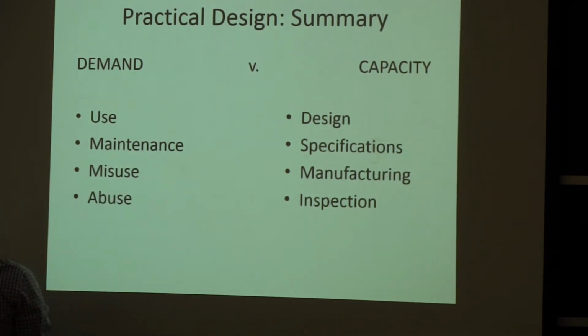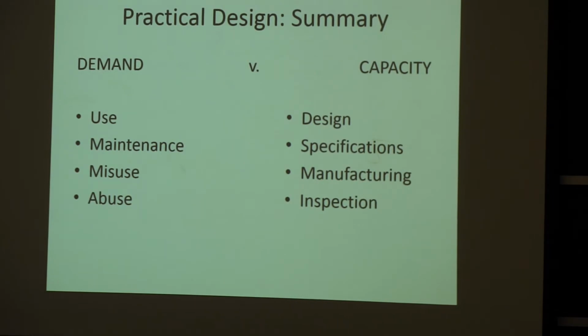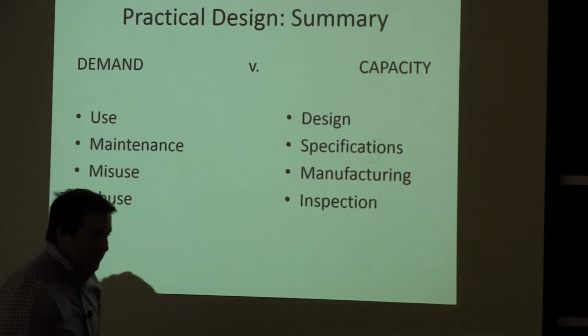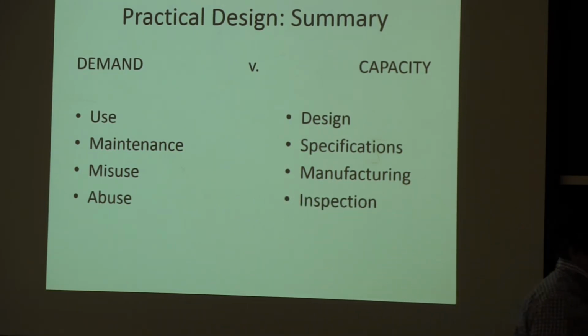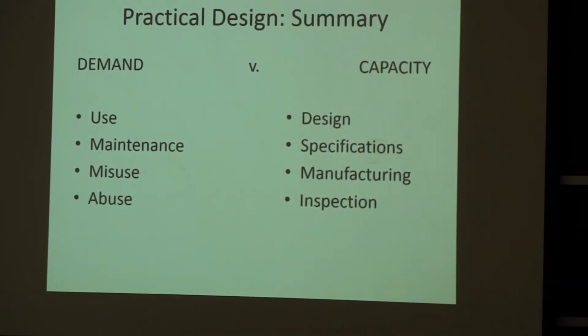If you don't have any quality control, I don't know that you can be sure, if you have a joint, that it will have any significant structural strength. If someone can do the weld exactly like they want to do it, maybe they didn't put in the shielding gas, the things that they really need to do, and if they don't do it, your capacity is not reliable.